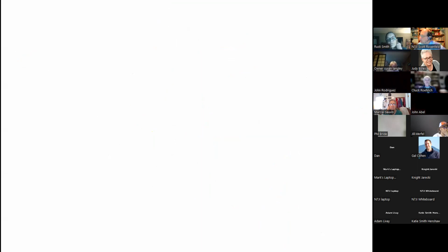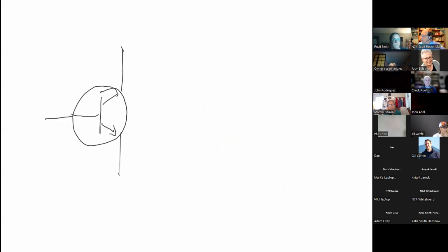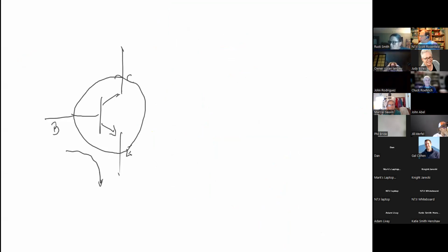How about if I do this? So this transistor actually is drawn like this. They're still the same thing. There's my base, there's my emitter, there's my collector. Okay, this is a 3-terminal device. If I have a small signal that goes this way, I have a very, very big signal that goes this way, which is a big copy, assuming I'm operating in the linear region.